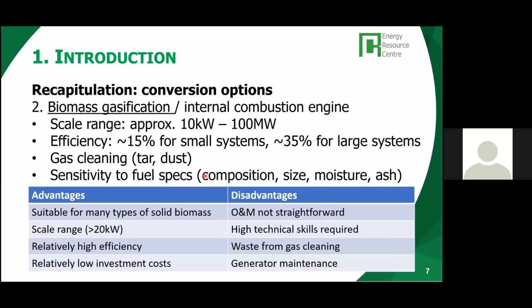Looking at gasification, in combination with an internal combustion engine, that's applicable from smaller scales upwards. You see that the efficiency is already at a higher level in comparison to steam systems at a much lower system capacity, and can similarly go up to, let's say, 35%. That might be on the high side because of the internal combustion engine efficiency.